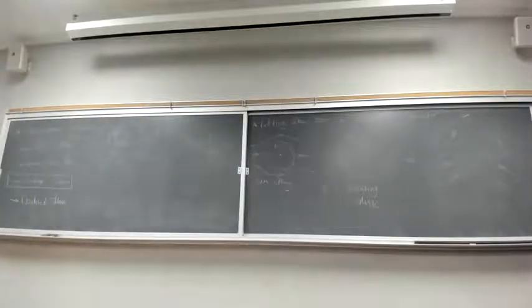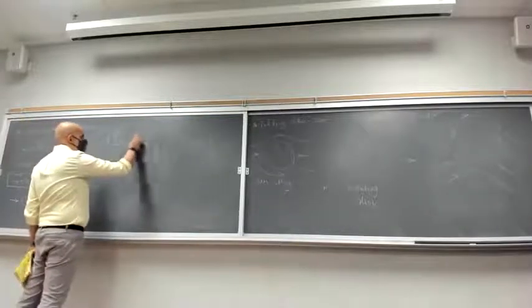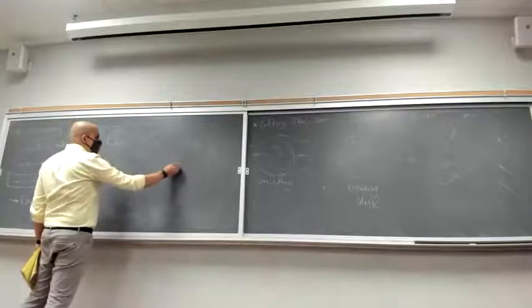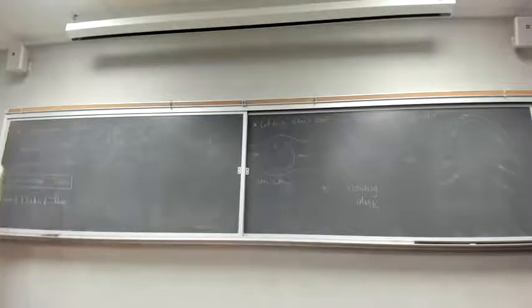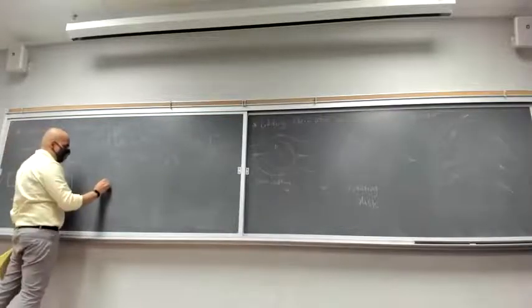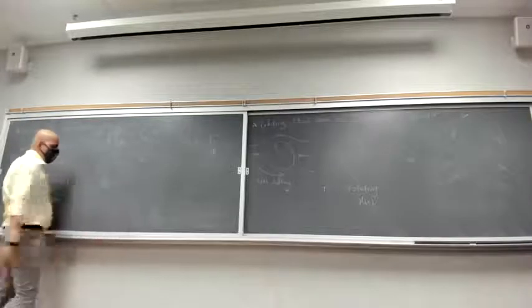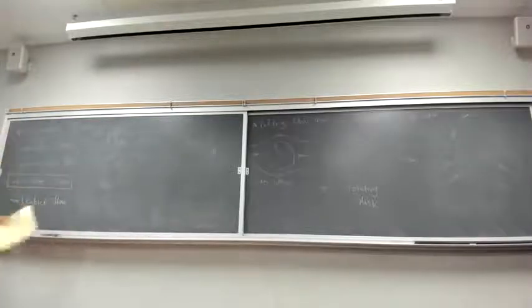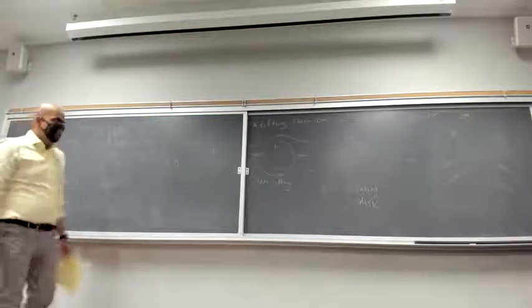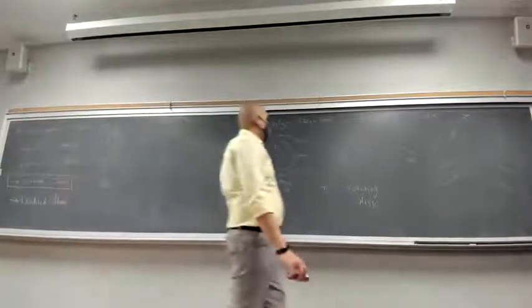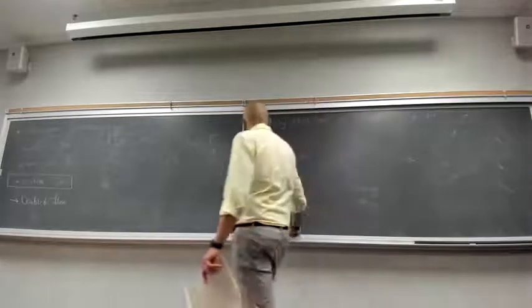Gamma here is the strength of your vortex. What about the stream function for this non-lifting flow, flow over a stationary cylinder? We never calculated this. I just gave you the velocity values, V_r and V theta. The idea was we are going to come back to this and do the calculation.